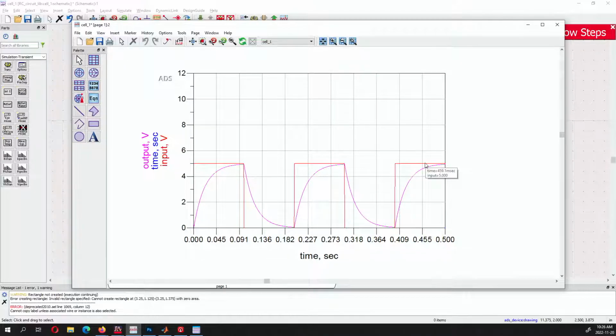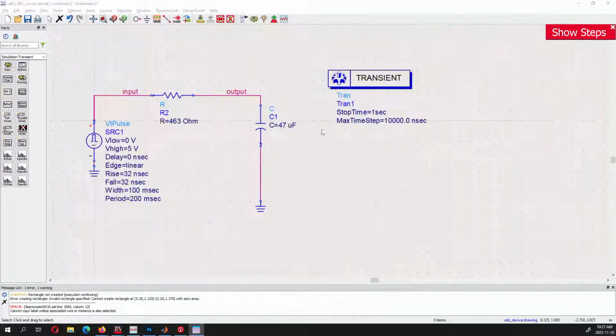So that's the second way of analyzing your circuit: using a SPICE simulator and figuring out what your circuit is doing, its behaviors, giving it different inputs to see how it behaves. You also have the mathematical representation if you understand how to derive the circuit using pen and paper. It gives you an even stronger feeling if your math solving it by yourself matches the simulation. That is great, and if your simulation matches the actual experimentation, it really strengthens your understanding at a deeper level. That's really what we're aiming at over here.